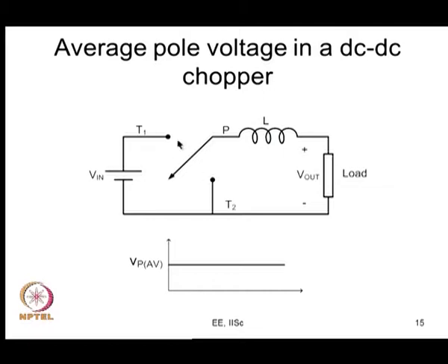So, with these switches, normally power flows in one direction. If this is a regenerative load like a DC machine, you could actually make these switches conduct in both directions, and you can make this a regenerative chopper. So, you can make it a 2 quadrant chopper also.